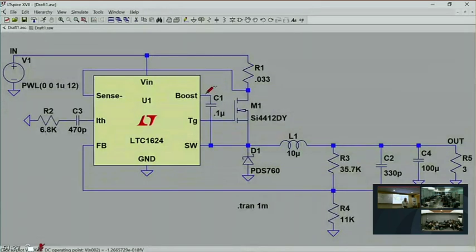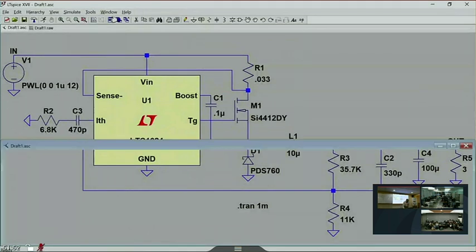Now, when the controller tells the gate driver to pull this thing high, you still have current flowing through the LDO and the diode, but eventually it'll start enhancing the channel. And then, when you start enhancing the channel, this node will start slewing positive, and this pin will bootstrap the boost pin with it. So we can watch this, we can look at these waveforms.